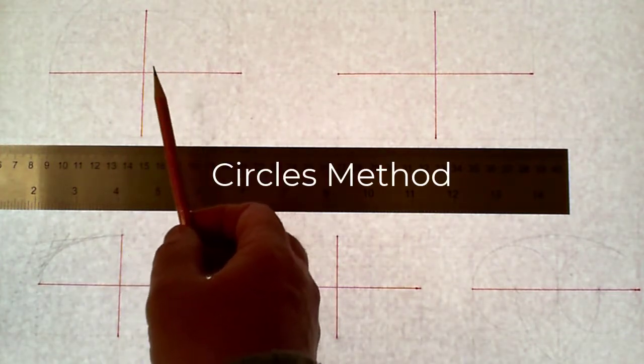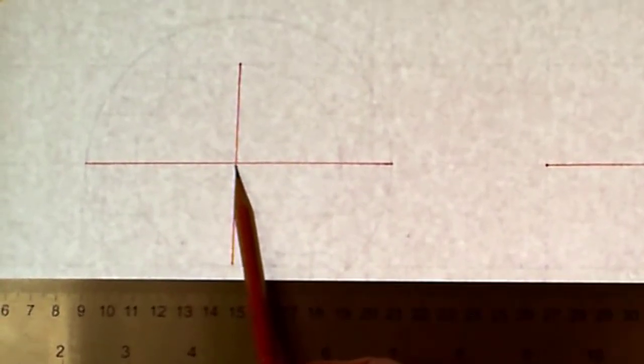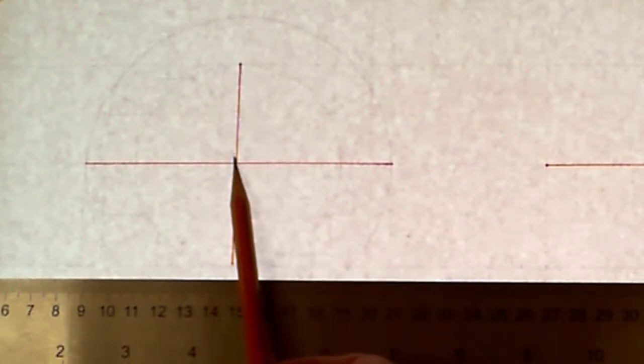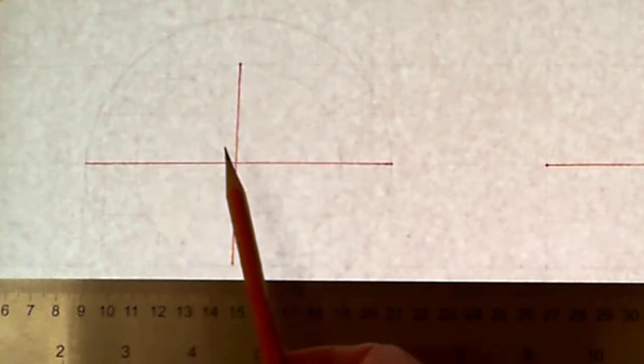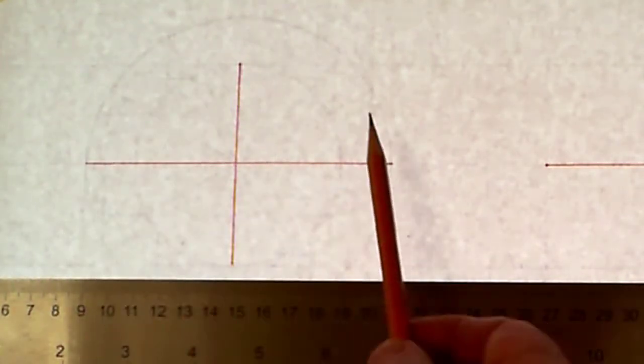What you're simply doing is using the intersection point of the major and the minor axis as a springing point, and you're going to use as a radius half the minor, and draw a circle, and then you're going to use as a second radius half the major, and draw a circle.